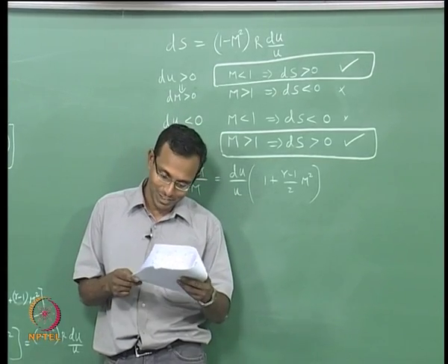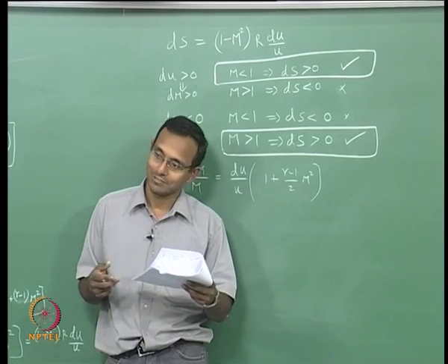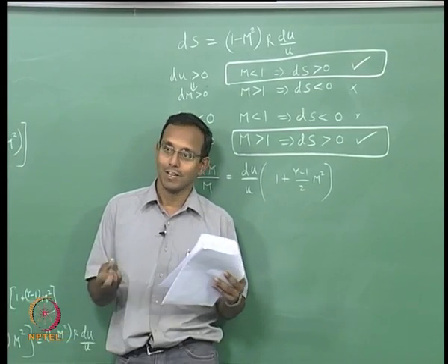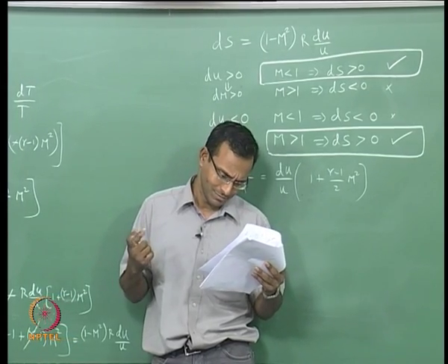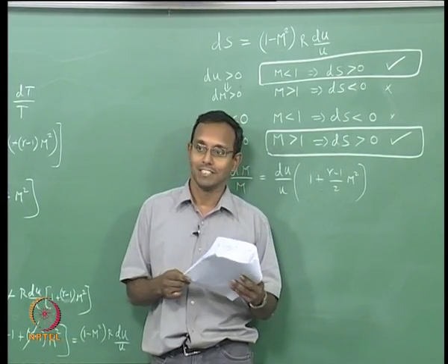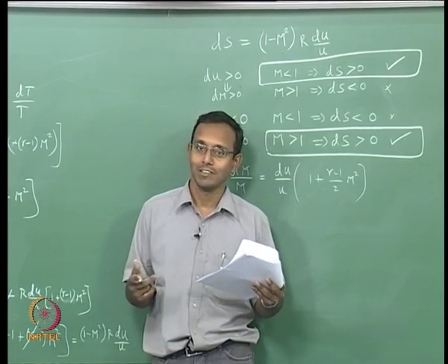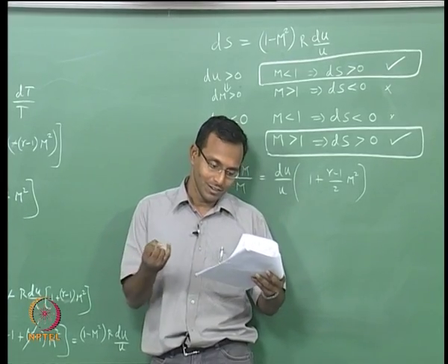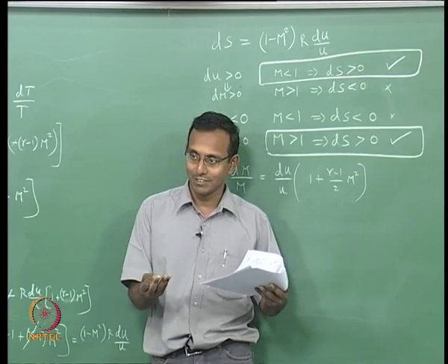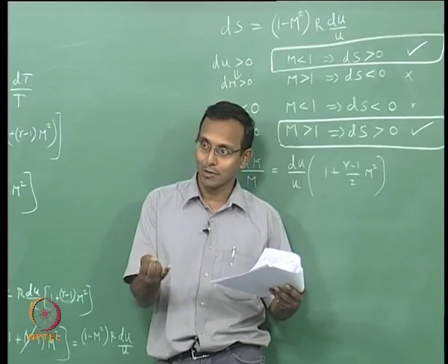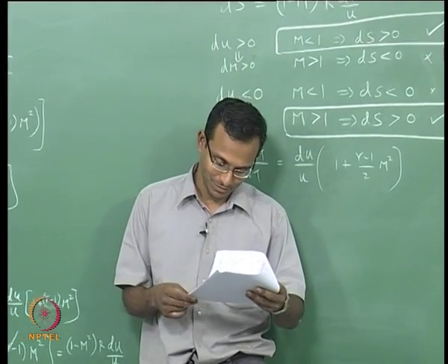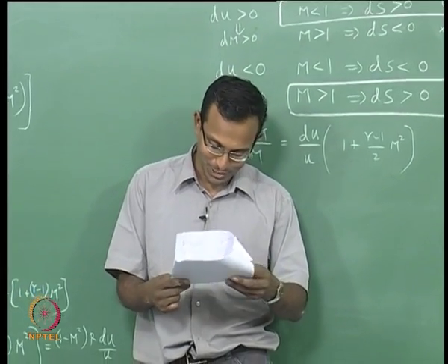We had 6 equations and 6 unknowns: mass, momentum, energy, state, entropy and Mach number definition. The unknowns are pressure, density, temperature, velocity, Mach number and entropy. You need all of them to actually solve the problem.